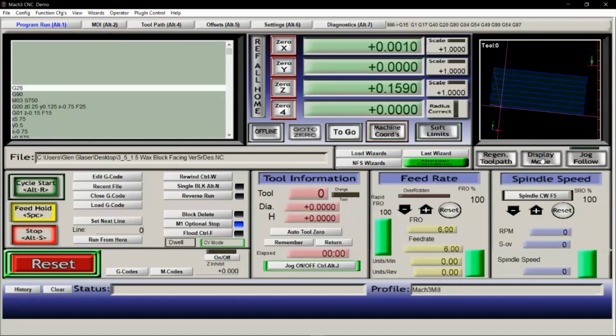This display bar has two functions. This first function we're looking at is just looking at the G-code and your toolpath. When you click display mode again, it will display an outline of where the machine is allowed to work in and is not allowed to cross over. When you have jog follow on, you will know when it's on when you have the LED lit. It will just basically follow the jog of the spindle as it goes through each toolpath function.